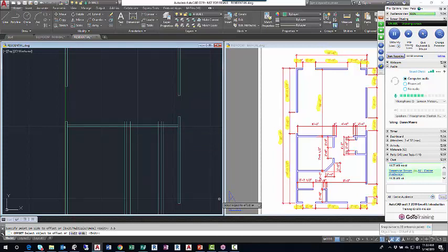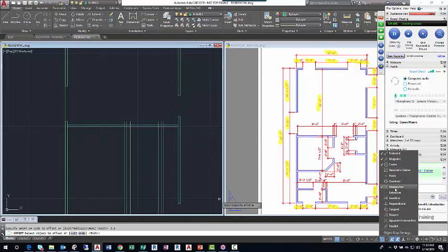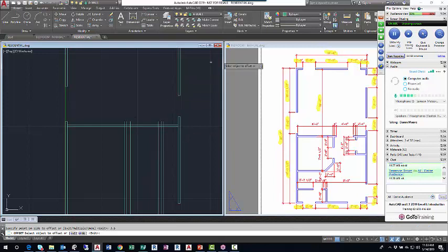I'm going to turn on intersection, and I'll go distance command, endpoint to the intersection of that first, that's 2 feet 1. So that indicates that I don't really need to put the 2 foot 1 inch offset in. It's been put in by my final offset, which was 3.5. So that was 6 offsets. And kind of a shortcut to get there.